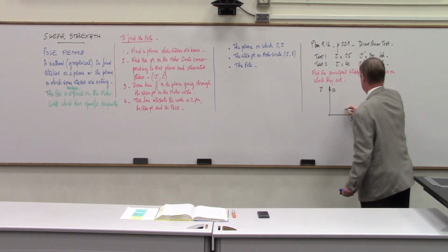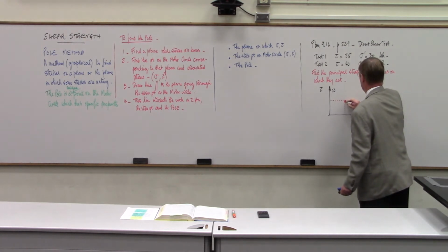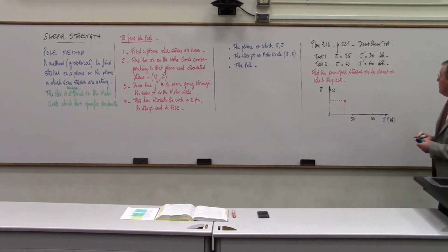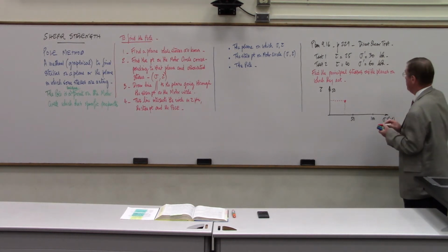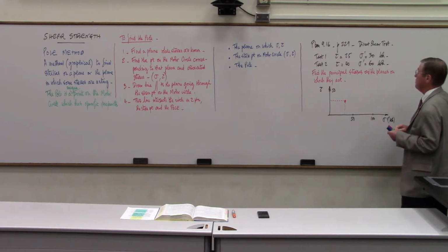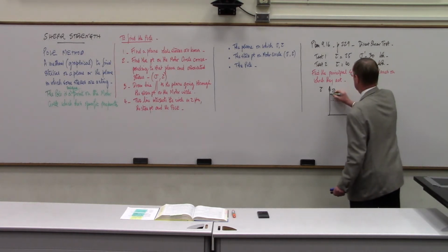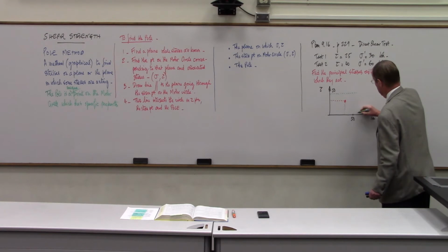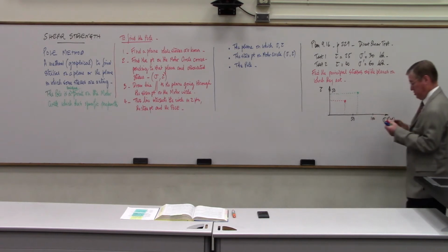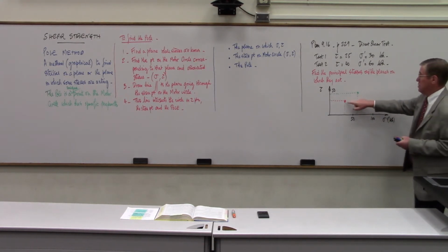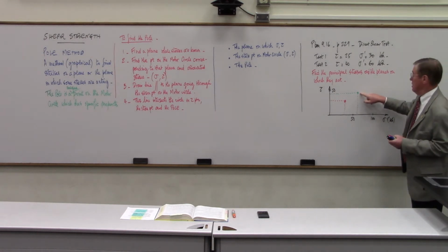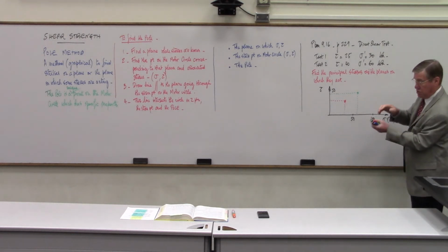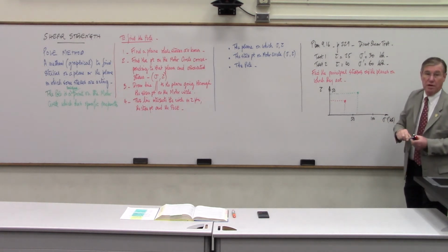So 30 is right here, and I had 25 right here. Okay, so I had 1 point right there. And then I had another point at failure where tau was 40, so right about here. And then sigma prime was 60, so right about here somewhere. Okay? And that was the second point. Because these 2 points are corresponding to failure in shear, they must be on the failure envelope.